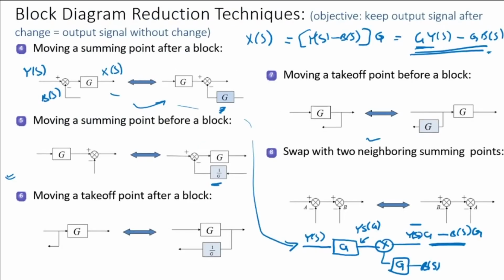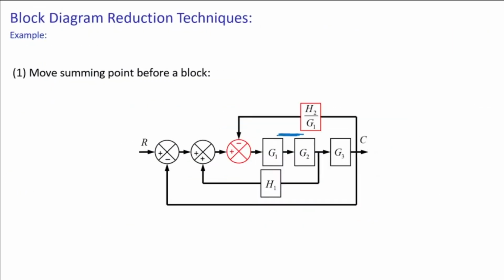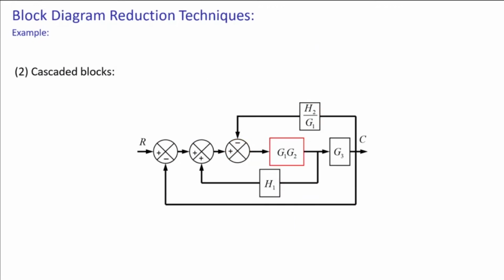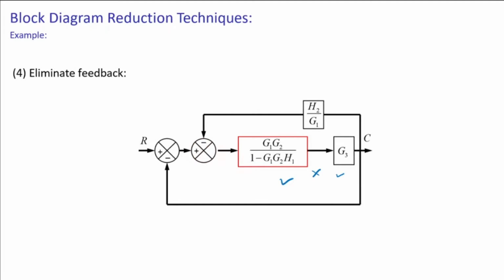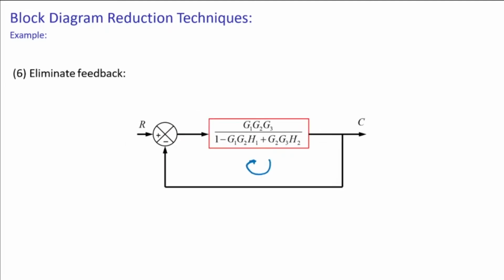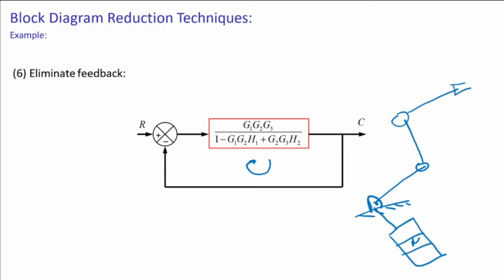Now this is again something to remember here, that we are talking about single input, single output. Okay, so what you see very clearly here is that there is only one input and there is one output. But we said that in a robotic system we have two inputs. Now what are those two inputs? This is my robotic link and this is my manipulator. Now as far as the controller is concerned, the controller is only controlling the motor. There's an encoder gear in front, so it's controlling the voltage to the motor. And the controller does not know what is happening on any other joint. So this is what we call independent joint control.